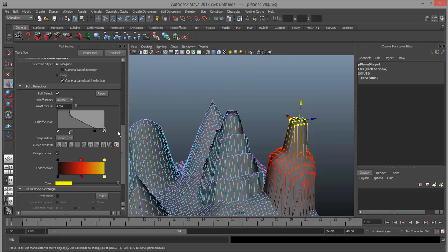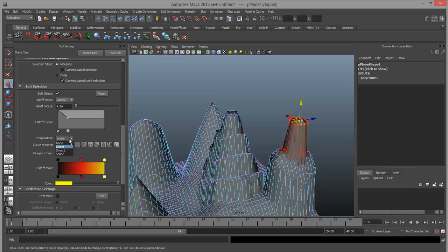And you can do other things too. So let me delete a couple of these. Boom, boom, boom. That one, that one. So I've got this point which I can move around. The interpolation setting here can be changed to none, linear, smooth, or spline. If I set it to spline, let's see. If I click it in a second spot and turn it to spline, there we go. You can see it gets a nice smooth kind of interpolation.